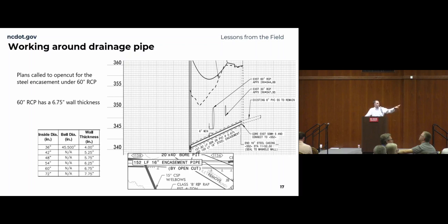So if the original anticipation was just put the bore encasement pipe 6 inches below the invert, you're touching. So we run into items like that, even when we're phasing it, and we start getting into, do we need a cradle sometimes or pouring flowable fill around it? A lot of municipalities still have minimum requirements that there has to be some sort of separation between the two.